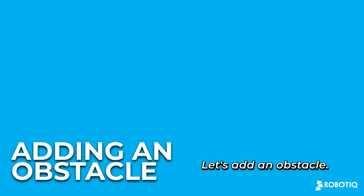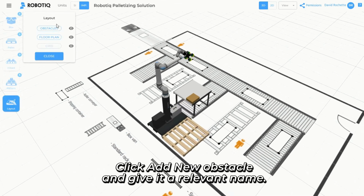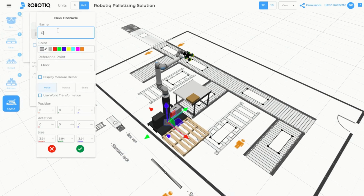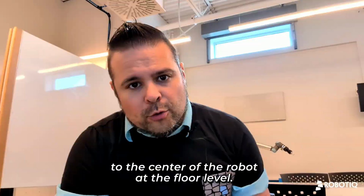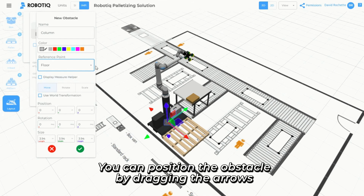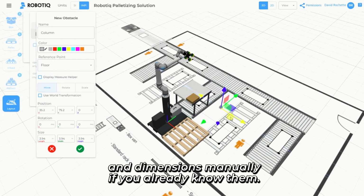Let's add an obstacle. Start by clicking the Layout menu, click Add New Obstacle, and give it a relevant name. Select your reference. In most cases, you'll use floor, which corresponds to the center of the robot at the floor level. You can position the obstacle by dragging the arrows directly on the screen or by entering the position and dimensions manually if you already know them.